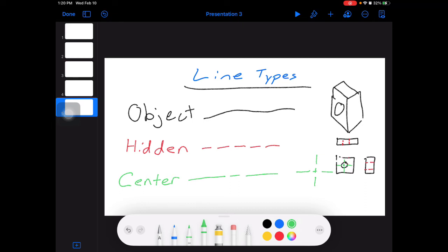of that circle. Also, in our top view and our right view, right now we have just the edges drawn. We don't know if that object is a square or a circle just by looking at our top and right views. So to make sure we say it is a circle, or a cylinder in 3D going through this object, we're going to draw center lines through the center, to the best of my ability, of those two views. Think of that as a wheel and an axle. Your axle is your center lines for where your wheels spin or go around. Just like here, I drew the center lines in my top and right views, just like an axle. So those are object lines, hidden lines, and center lines.